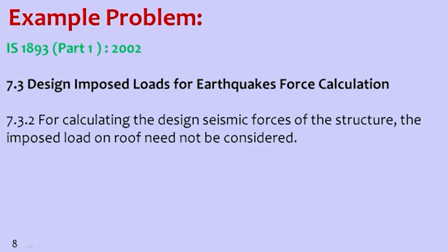The second clause on the same imposed load suggests that we avoid the imposed load on the rooftop for the seismic mass calculation.